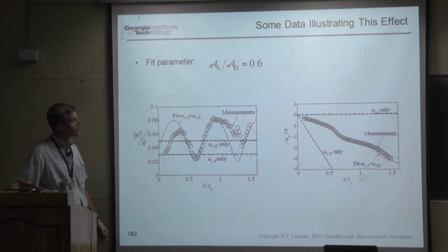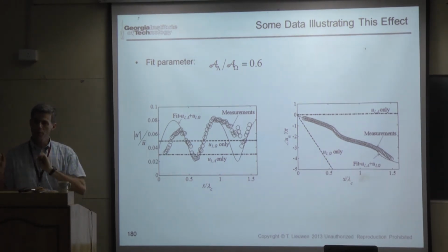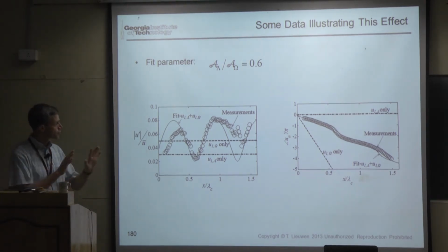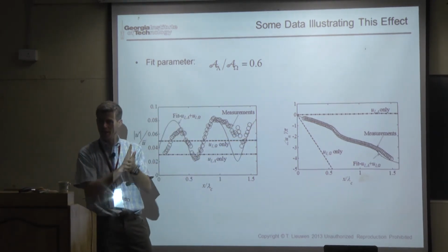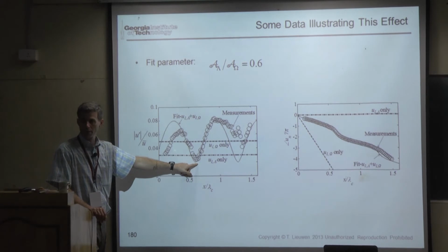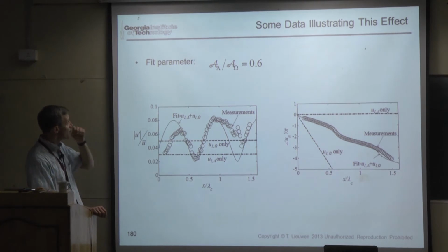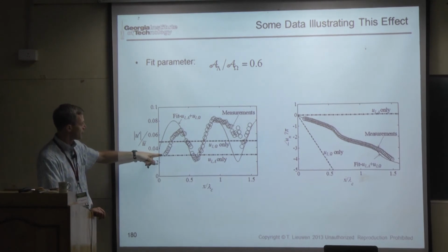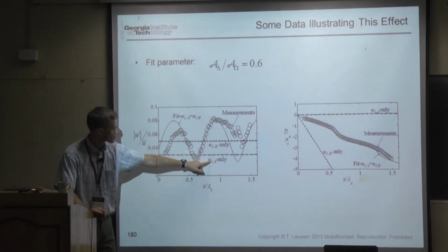All right? So what you're seeing here in this case is when you take two disturbances with the same frequency, but they're moving at a different phase speed, what you're basically setting up is an interference field. All right? And so you have these two disturbances, one is moving fast, the other is moving slow. At some points, they're exactly in phase with each other. You get big amplitudes of oscillation. At other points, they're 180 degrees out of phase with each other, and they almost cancel each other. Now, if you plot the individual vortical component amplitude as a function of x, it looks like that. The individual acoustic contribution only looks like that, right? That's what I'm trying to show here.